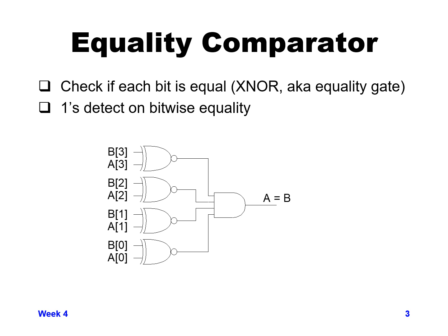If all of the outputs of all of the XNORs are 1, then we get a 1 out of an AND function. So for an equality comparator, basically we want to do an XNOR of each A versus B bitwise to each other, and then follow it by an n-bit AND function.